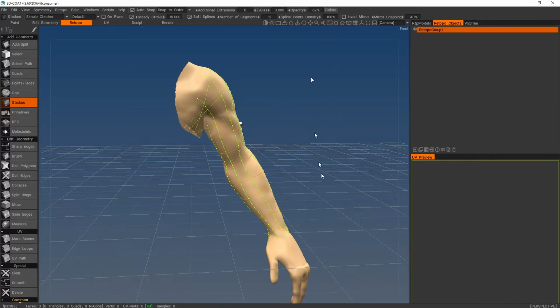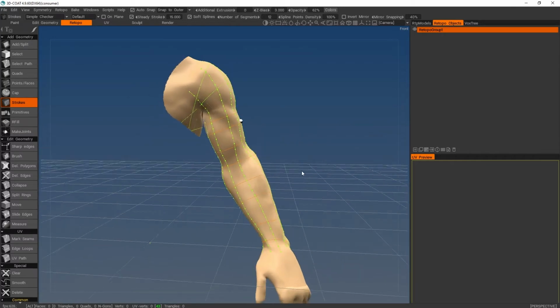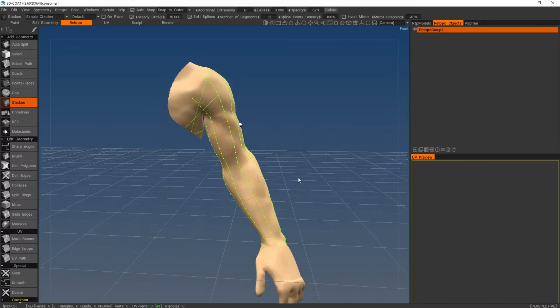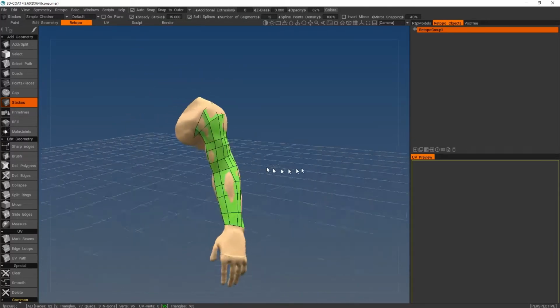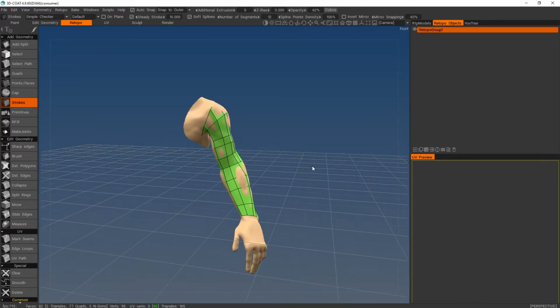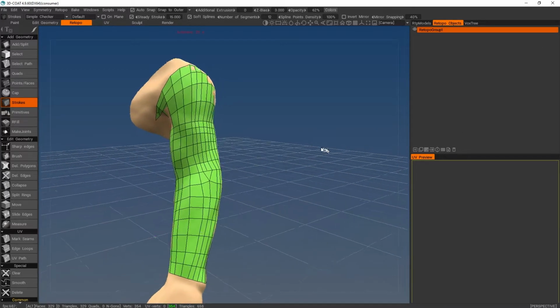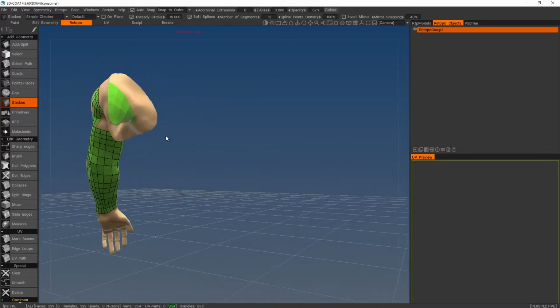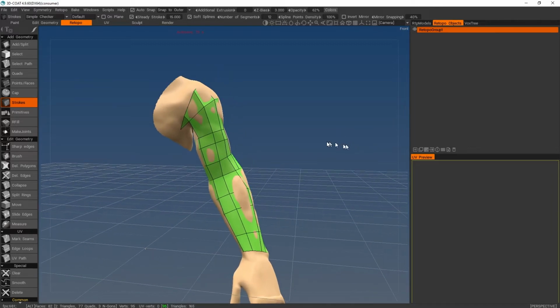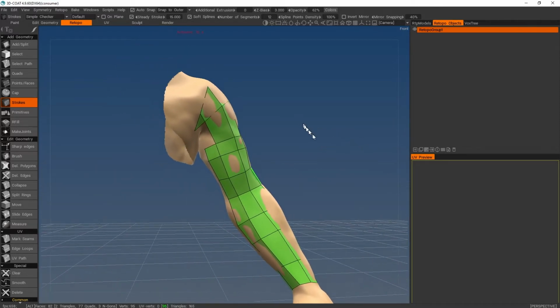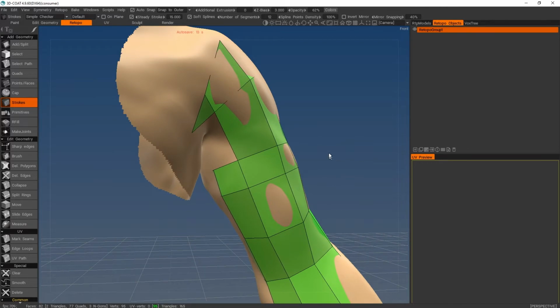So once you've got your strokes tool and you've got everything reasonably in place, you just hit enter on the keyboard and it will go and generate a low poly version of the model. If you've got your retop group selected, you can just subdivide it to add more geometry. And yep, that's a pretty good sleeve. I'm actually just going to tidy this up a little bit more.